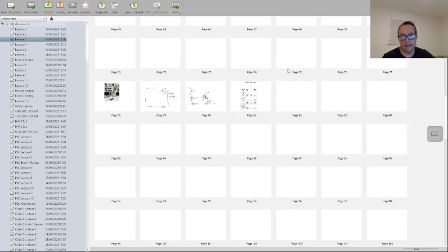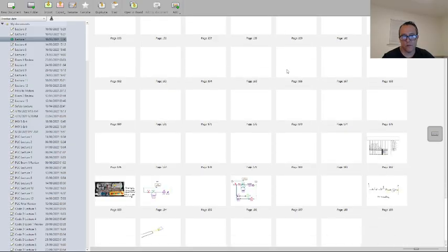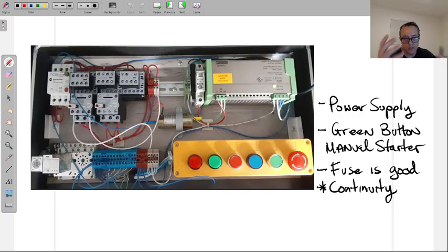And in person you have it, online you have it as well. So I'm just going to use the online one just because, again, it's a way bigger close-up image. This is our power supply here. So the idea for in-person students, online students, is they plug that in, receive 120 volts, and then the 120 volts kicks out 24 volts DC from the secondary side.